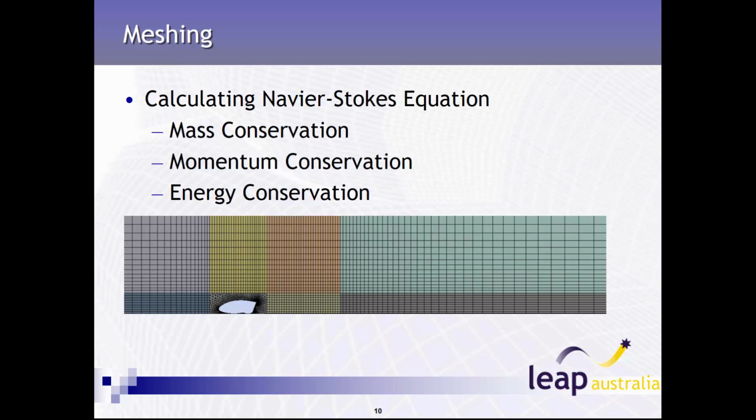A coarse mesh may be quick, but unable to capture the flow characteristics. A fine mesh may be accurate, but encompass high computational resources. Determining appropriate mesh size takes time, and we'll go over different techniques and principles.